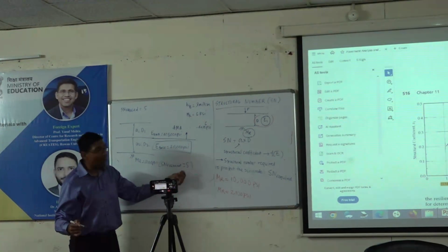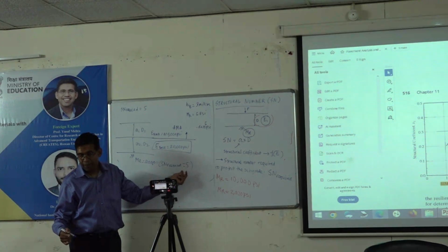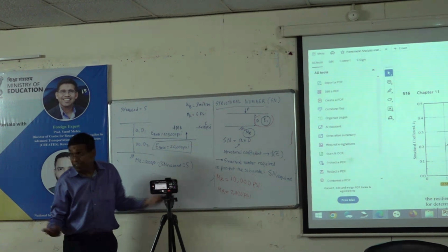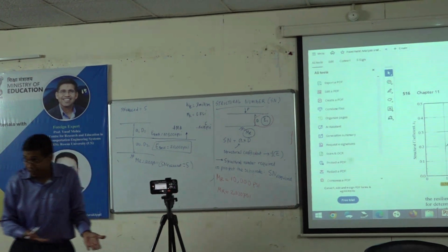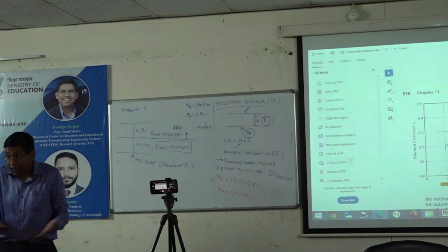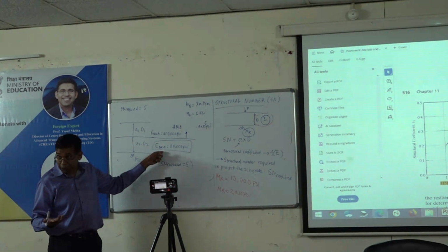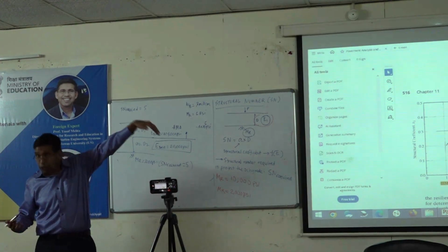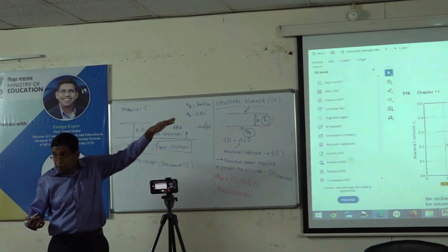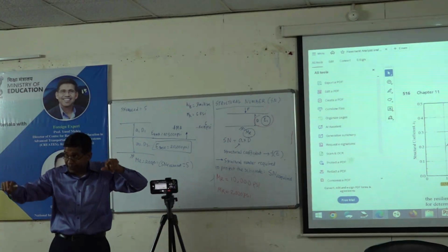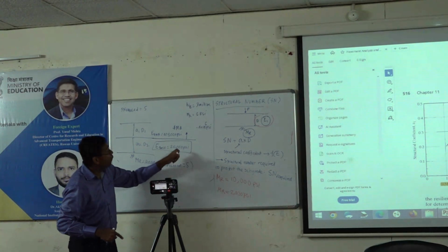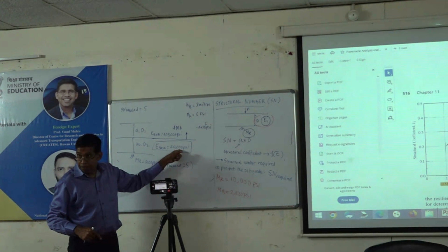Will it be more than 5 or less than 5? Less than 5, it is stronger. I just discussed it earlier. It will definitely be a number less than 5 because 5,000 is less than 20,000. So you have to go back to the nomograph that I showed you, go through the whole process and get the SN required to protect this base layer.